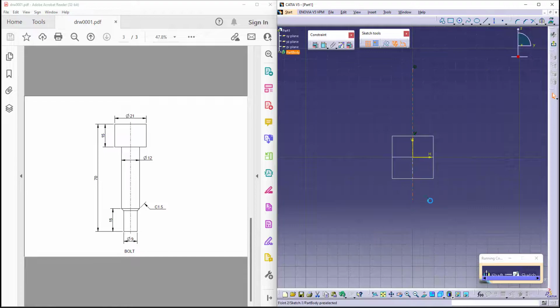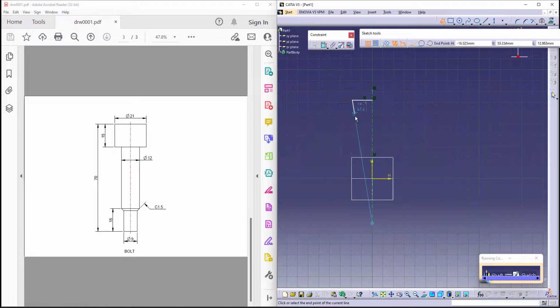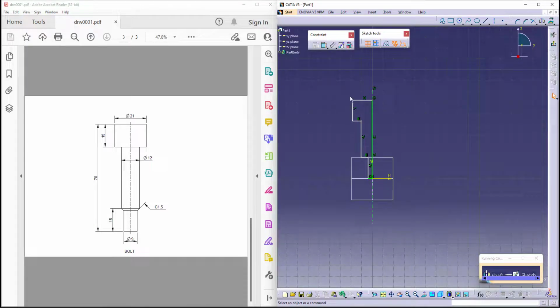And then I'd like to make my sketch. Now if you're trying to make it directly, you can do so by directly taking it this way. And create a shaft after giving the dimensions. Or if you want, you can go ahead with feature based modeling, which you can directly take the whole rectangle in one attempt and then start removing the material one step after the other using your groove command. The first one is better for me, so let me try to do that only instead of going ahead this way.